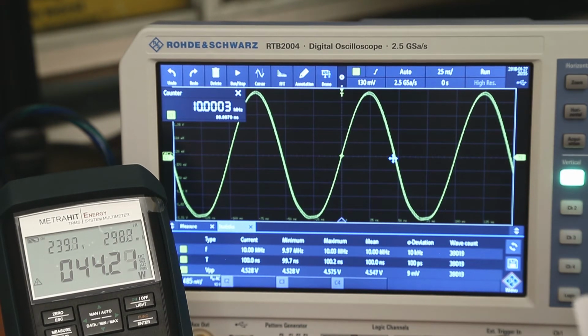Funny enough, with the Keysight, I switched the screensaver on and it went down by about 4 watts, so the screen of the actual Keysight is drawing about 4 watts itself. There's no screensaver on this, so I can't do the same experiment, but even with the screensaver on, the Keysight's still running in acquisition mode, but with the screen not being driven with any backlight, it was running at about 62 watts as opposed to 66 at maximum.